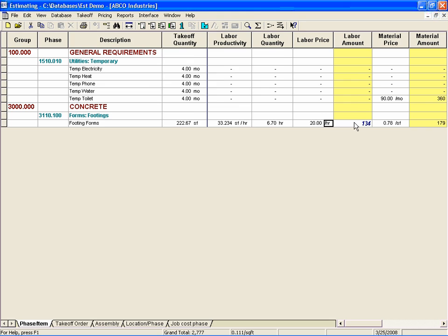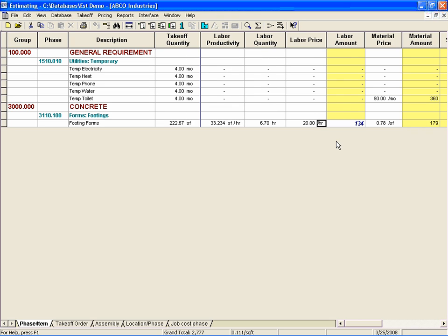At this point, you're hopefully recognizing the benefits of estimating in the back-end database. However, the real power lies in the ability to take off groups of items all at once. That's where assembly takeoff comes in. A similar drill-down process is used for selecting the assembly from the database, but this time, once selected, it includes all the items that make up that particular construction system, such as a wall or a concrete slab, as well as the dimensions required to calculate takeoff quantities and costs for each item. Let's walk through the process.